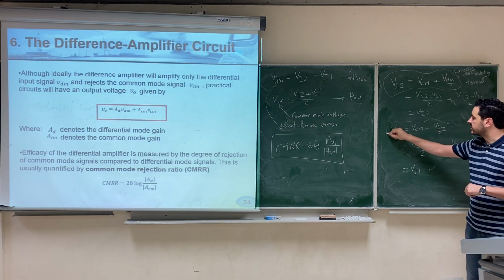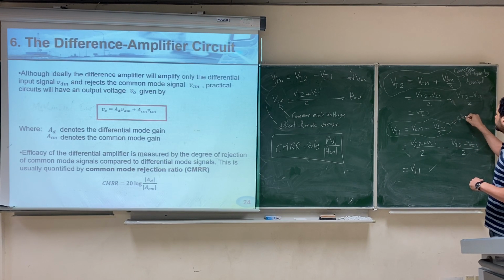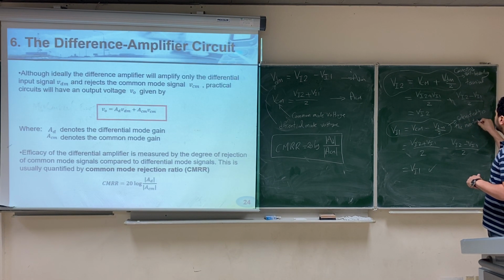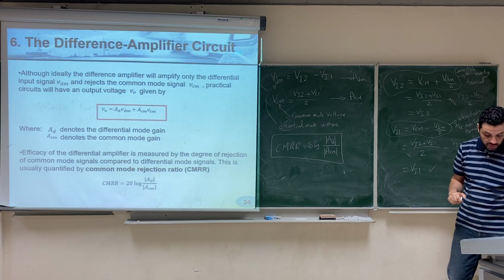So we can write the source connected towards the inverting terminal as V common mode minus V differential mode over 2.